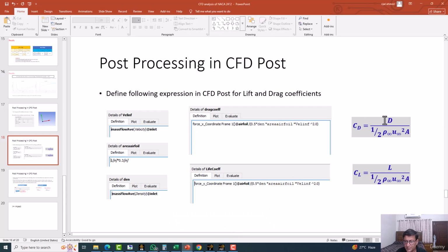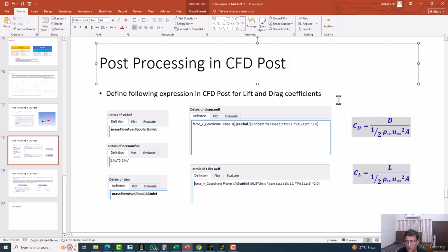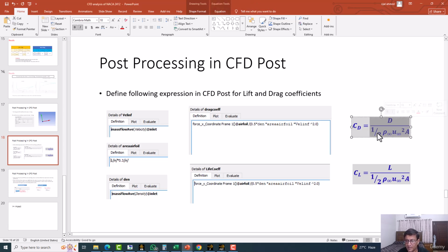So if I want to get the drag force for some other aerofoil length and area, I will simply multiply the CL and CD by 1/2 density, velocity squared and the area, and I will get the force for that particular dimension, or the particular material properties and flow properties. Okay. So now these should be defined, like area, density and velocity, with the proper units. This is very important.